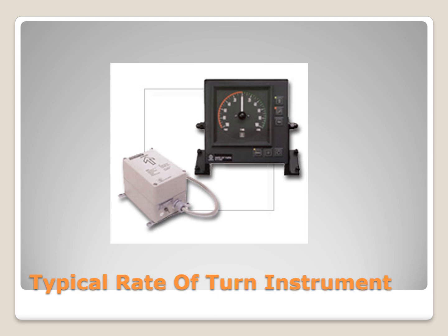For seagoing vessels of more than 50,000 gross tonnage, as I mentioned before, it is a requirement that this equipment is carried on board. Repeaters may also be fitted to the vessel at different maneuvering positions to indicate the vessel's rate of turn, and by different maneuvering positions we mean the bridge wings, port and starboard. It is also worth noting that some modern gyro compasses will provide the rate of turn output as a standard additional feature, and so a separate rate of turn gyro does not need to be employed by the vessel.